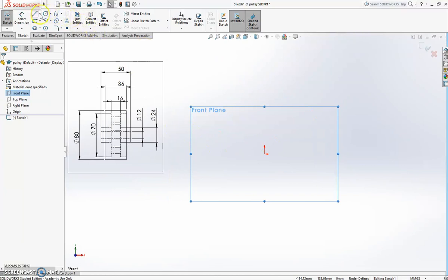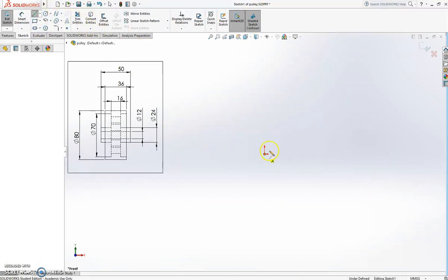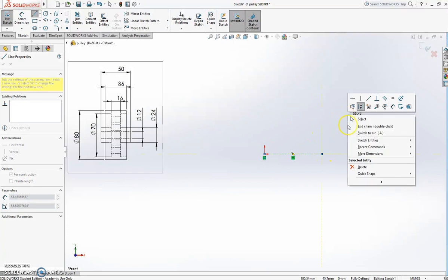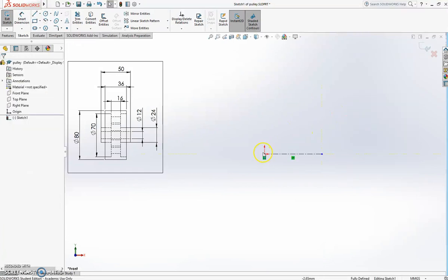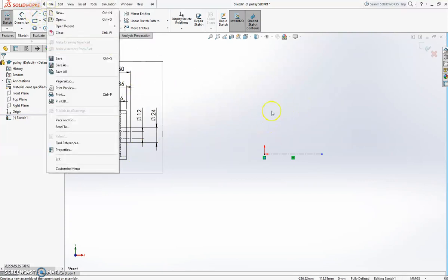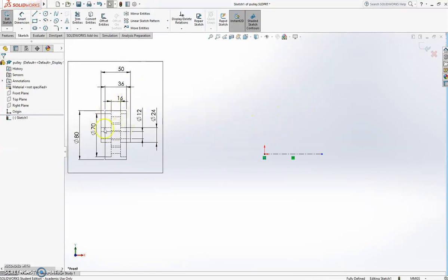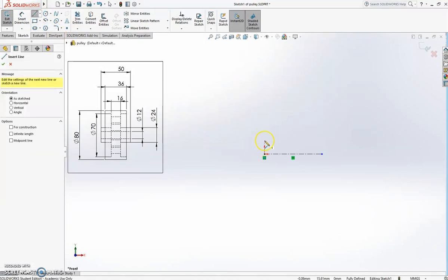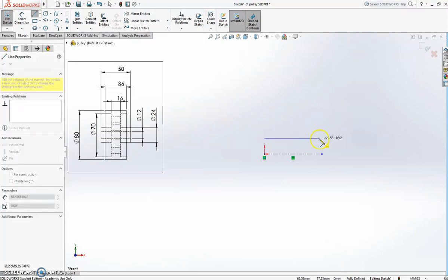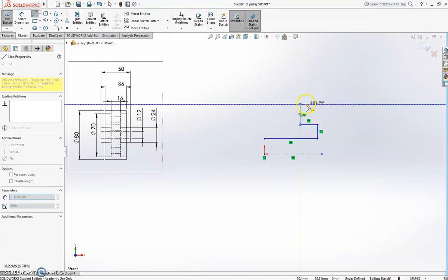and I'm going to start with that center line. So I'll do the center line from the origin, and as I said, that then will leave the origin of our part here at the center. I'm going to use the line tool then to just sketch out this profile. So I can select it up here in the toolbar, or I can hold the right mouse button and go left to get the line tool. And I'll start with that line just directly over the origin here.